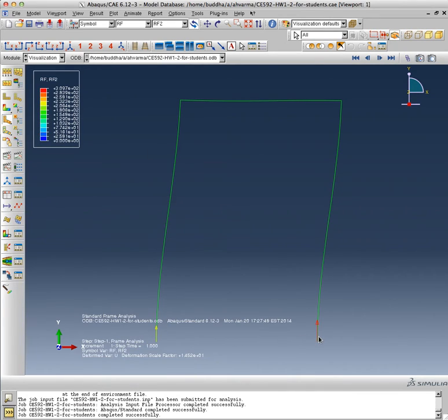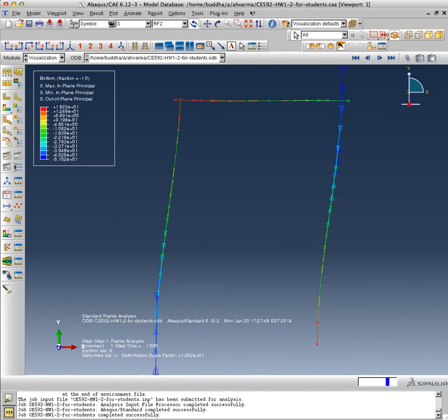Once again, you're looking at that. And of course, you can pick out the values using the probe values tool, which I showed you earlier. You can save the results. You can make different plots, and of course you can look at the individual stresses in the different beam elements as well. So for example, you can look at the stresses, although you probably don't want to look at it by symbol.